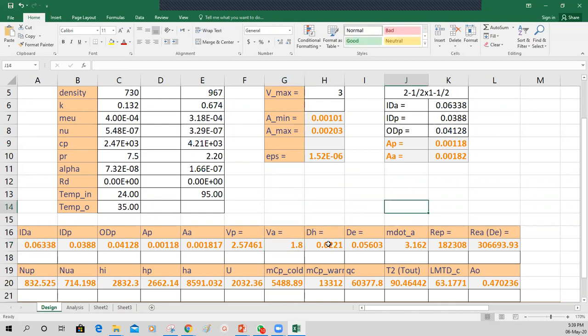And then we calculated the hydraulic diameter for the annulus. The formula is given, direct substitution, find out the hydraulic diameter. Equivalent diameter. The velocity of the annulus is from the economic range of water, right? Exactly. There is an economic range of 1.4 to 2.8. So you can choose anywhere between, 1.8, 2 or 2.2, 2.1, whatever. Okay. And then we calculated the hydraulic diameter, equivalent diameter.